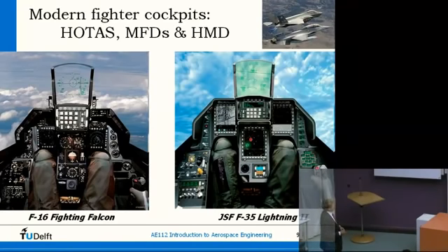The EFIS that they have has a different name. They have basically a multifunction display, and on any display they can give any function, though they tend to have some procedures for that. Here are the basic standby instruments. They get smaller and smaller also in military cockpits. I cannot locate them here right now. You also see that until recently, standby instruments were always mechanical, while nowadays standby instruments can be a computer screen, as long as they have an independent power supply and are autonomous.